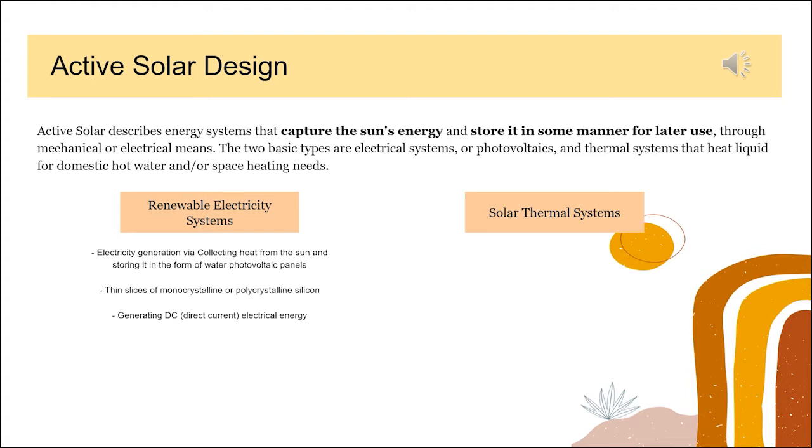Optimal orientation, slope, and weather patterns are really important to achieve good solar energy accumulation. And the panel usually will be installed facing south with approximately 30 degrees above horizontal. As for the benefits of using this system, there are many companies that offer lease programs where they will install and maintain your panels, while the residents benefit from the power produced and reduced energy bills, while the company gathers any rebates.